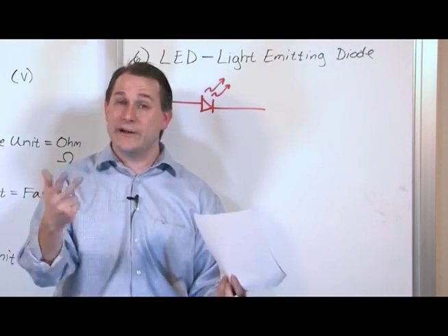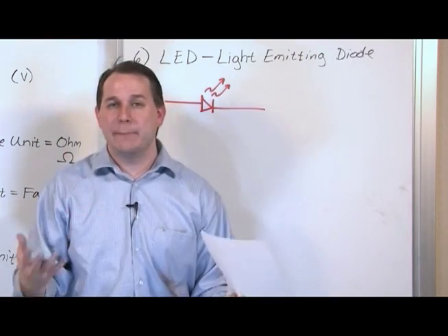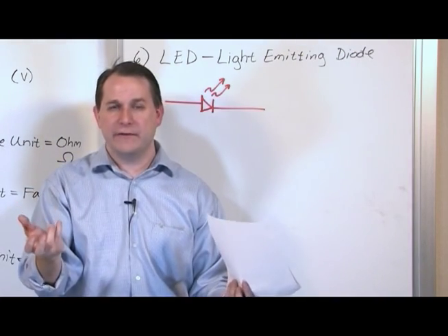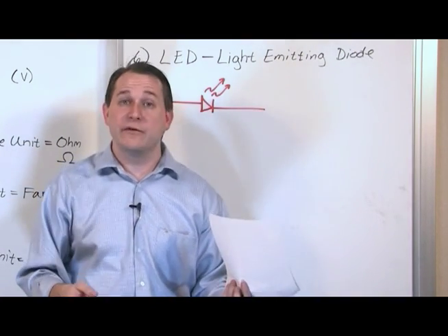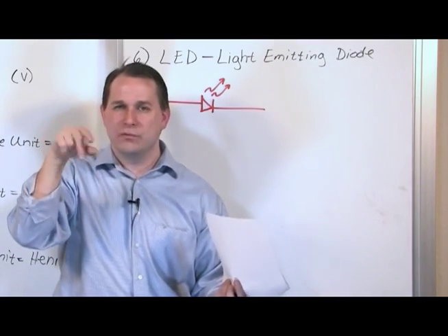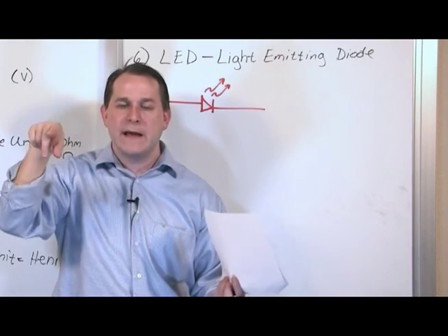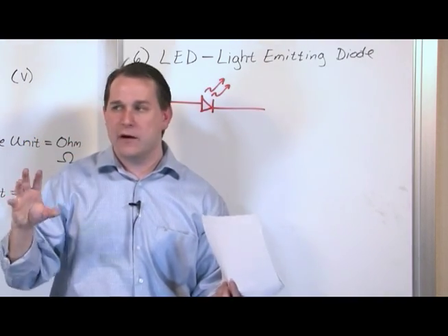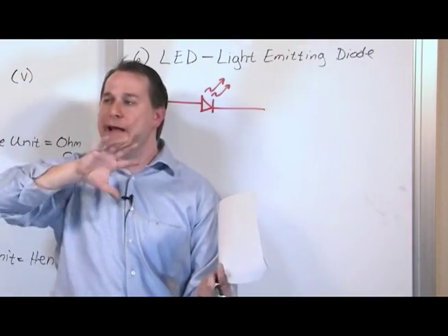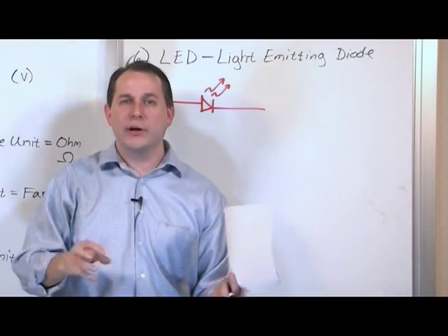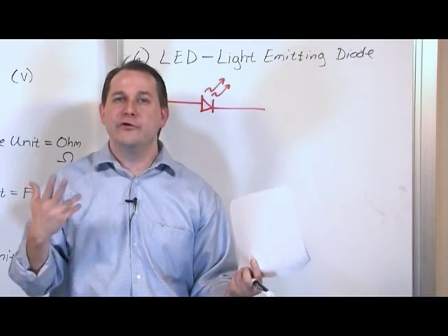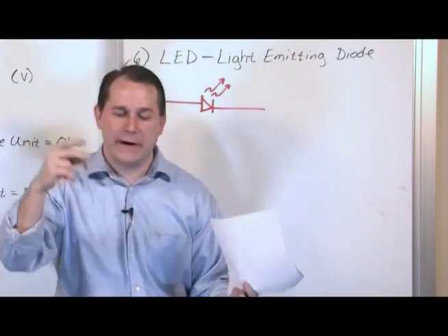A transistor's second function is that it can act as an amplifier. Literally, when you turn the volume knob on your stereo system, you're basically manipulating those transistors in there to push out more current. So a transistor can take a teeny tiny input signal, like your voice, maybe coming in on a wire, and it can make a direct replica of it on the output, but much bigger, much higher volume level, for lack of a better word. And that goes into your speakers, so when you adjust your volume, you get a nice, rich, beautiful, loud sound. That's a direct result of a transistor. So two functions of a transistor: switch and amplifier.